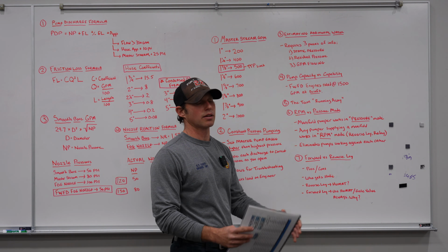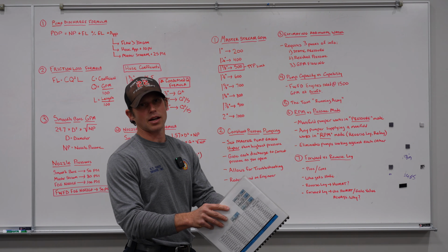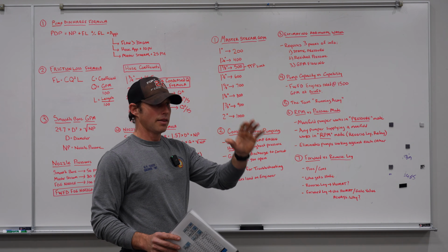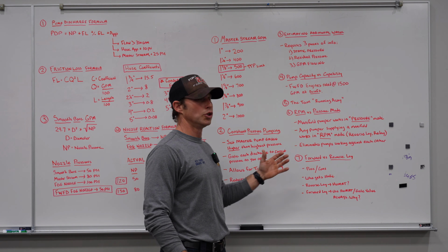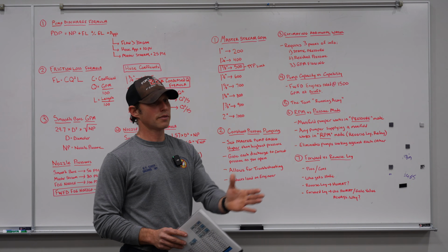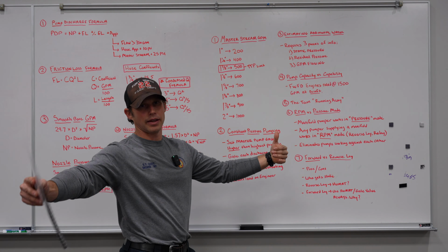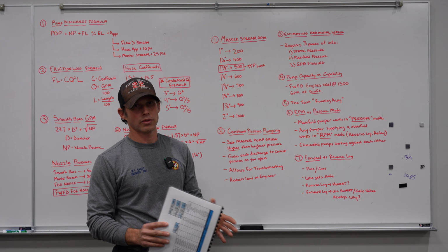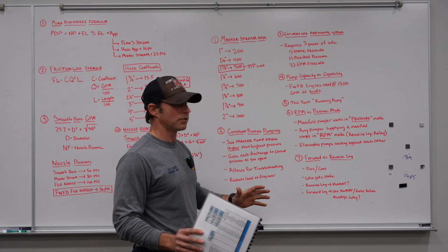Who gets the static pressure? This is kind of a confusing topic. When you do a forward lay and your line goes into the intake side of that manifold pumper directly from the hydrant, once he opens up his intake and he's getting that hydrant water, that manifold pumper is getting the initial static. That water is going straight from the hydrant into his intake. If you do a reverse lay, it's going to be the opposite. You're going to drop your supply line to the manifold pumper, drive down to the plug, and essentially hook your pumper in between the manifold pumper and the hydrant. So you're getting that supply line into your intake at the hydrant first, before that guy is. When you do a reverse lay, it's the guy that reverses out who gets the actual static.